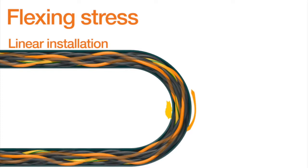And as you'll see, the small orange lines running parallel on the outsides of the cable, when it gets to that radius, that same point that we were looking at in the last slide, they're somewhat even. That's because of the shorter pitch length, the conductors are essentially subject to the same amount of force in the radius, as opposed to the layered cable that had one with a smaller and one with a larger radius that it was subject to.